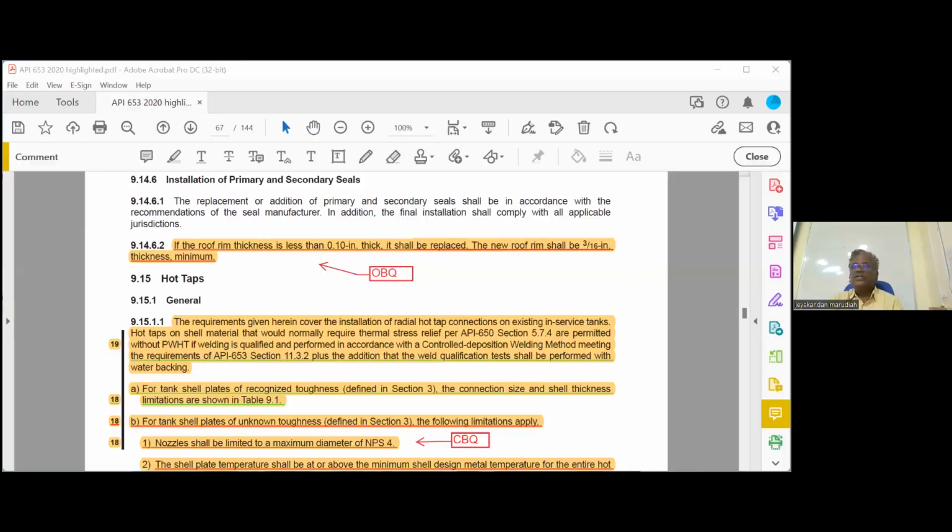Okay, so hot tapping should be done very carefully, because otherwise there is a chance of fire and sometimes even an explosion. Okay, the welding is the only critical part. That's because we are welding on the plate only. We are not welding on the hole. We are welding before cutting the hole. It will not catch fire.